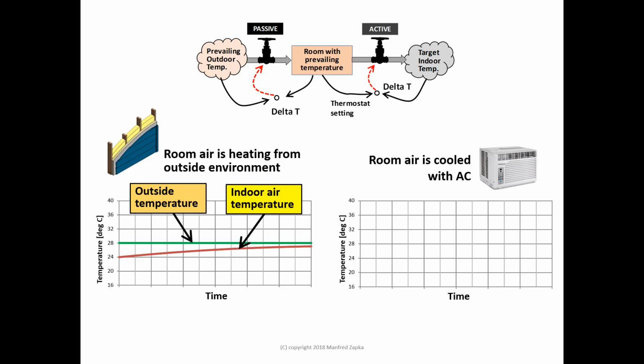Notice how the indoor temperature approaches an equilibrium, which is the outdoor temperature. Very noticeable is that the increase of the indoor air temperature slows as both temperatures approach each other. This temperature dynamics demonstrates the driving force of temperature differential which defines the conductive heat transfer rate. With larger temperature differentials, more heat is transferred.